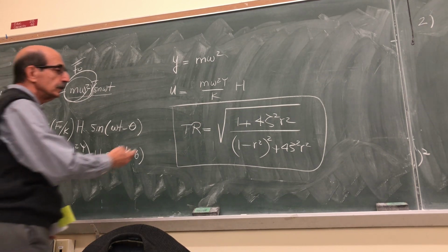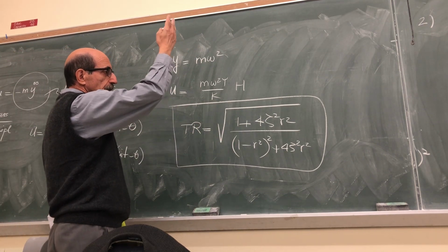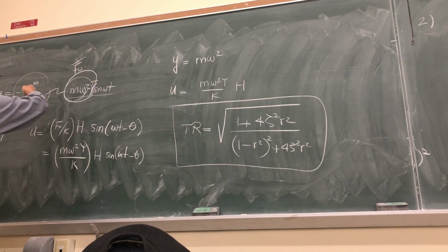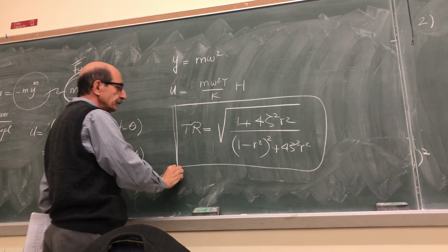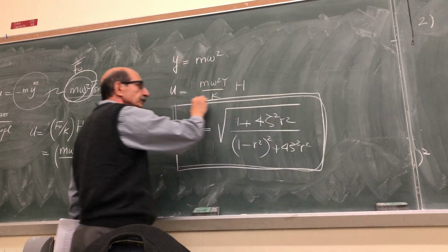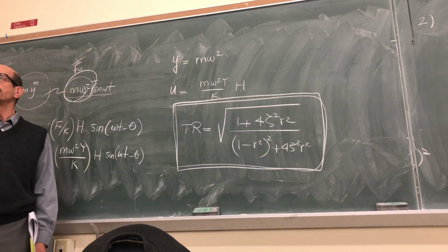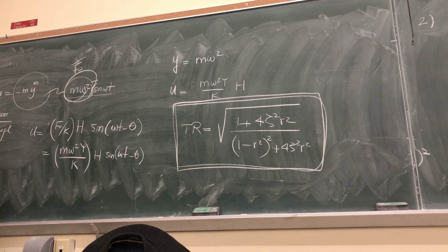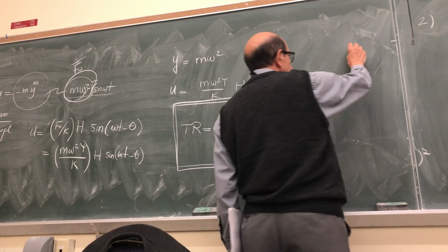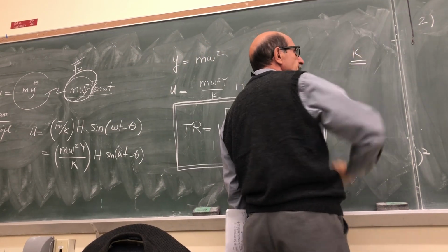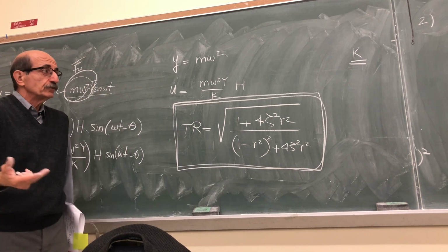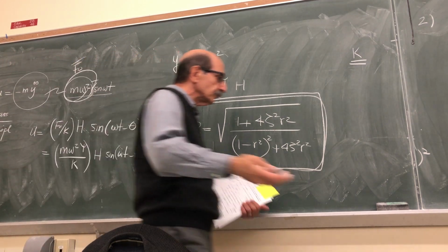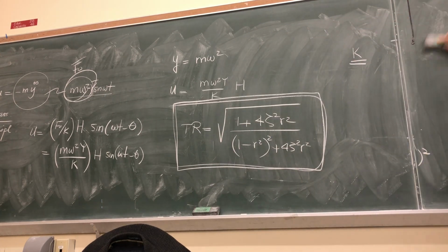Therefore, whether you are dealing with an input force on the system or the input displacement of the system, this is the guiding principle. This is the criteria in order to reduce the effect of the vibration, or in other words, to design a vibration isolator, which is basically this K. That's what you need to use. Of course, for each given case, the criteria given is different.